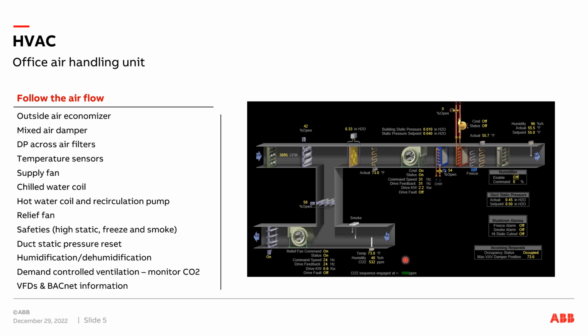One last thing I should probably mention is you see a little thing down here, CO2. So again, this was a little bit more pre-COVID, and some of the design changes have been altered since then. But what we would actually do is look at how much CO2 was in the room. So carbon dioxide, me and you sitting here today having a conversation, we're talking. When the CO2 levels would go up, we would bring in more outside air. When the CO2 levels would go down, we'd be willing to use more return air. So that was kind of a variable in how we controlled these mixed air dampers too. It wasn't just purely looking at the temperatures, we were also looking at the CO2 levels.